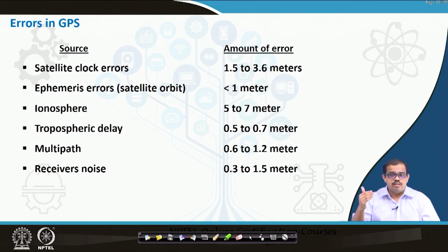Whenever you go to the field, first look at what the error in the measurements is. Switch on the receiver, and look at a known point on the earth surface that you are close to. Once you have the known point, if you look at the GPS point, you know what error is induced into the system.